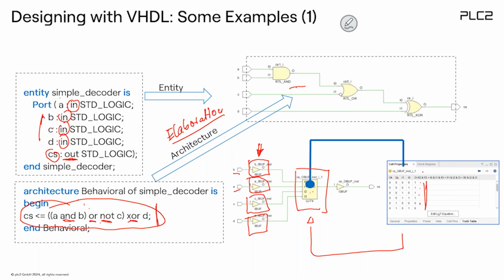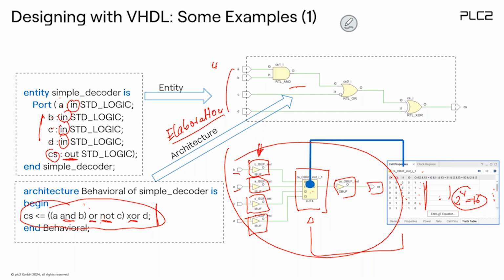Of course, it's just a snippet because you have to slide to see the complete window. In this case it's A, B, C, D, so we do have here 4 inputs. This means you do have here 16, 2 to the power 4. We do have 16 entries here, which are built into the lookup table. And then again, that would be the output buffer. And this is again the pad called chip select, and this would be my FPGA. So this is exactly what happened during synthesis.